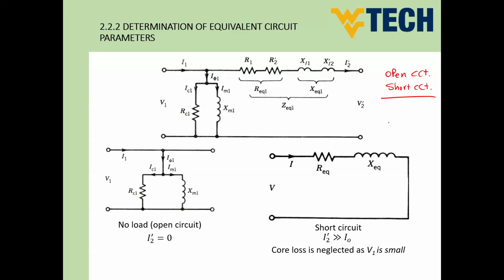In other devices or machines which work as a motor, we make what's called no load, which has the same meaning as open circuit here for the transformer, or in a generator as well. And we have another test called blocked rotor, which is also equivalent to the short circuit. So these are the well-known tests we use for electrical machines in order to identify the parameters. Let's start.